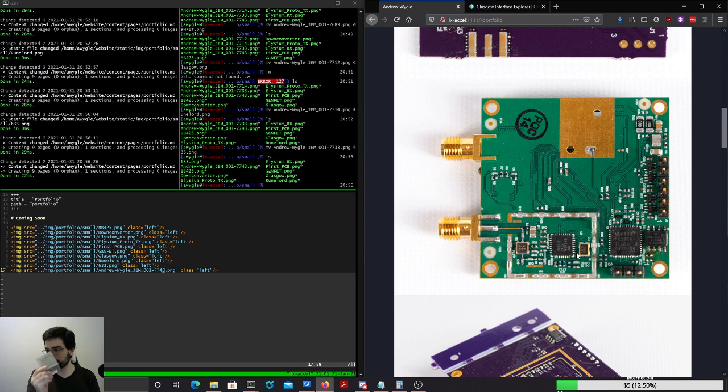So yeah, this has Sharpie on it because it's what's called a solder sample. It's basically there to let your manufacturer figure out their process and dial in the process parameters without having to burn a good board. Oftentimes they secretly work, and they just write on one of them like, oh, this one's broken, just because they didn't actually have any failures.